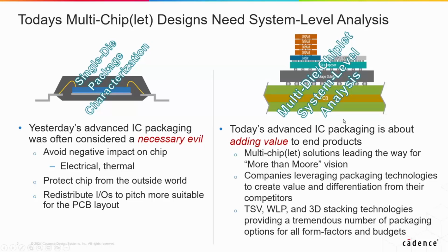I've spoken to many customers who say they look at the way they design their package as important as the way they design the actual semiconductor itself. And that has to do with the fact that we've gone to a more advanced packaging substrate that may include using a silicon interposer, stacking die, having multiple die within the package. It really creates a phenomenon in itself in how to make all the signaling and power delivery work within the package. But then, of course, it needs to work within the entire system. So this is what's contributing to this world of more than Moore.